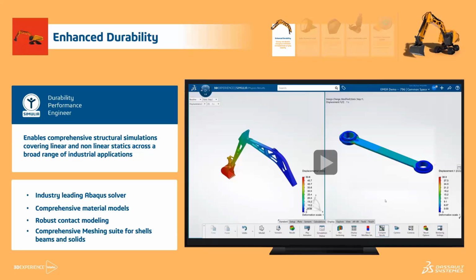Also, another advantage we have compared to our regular SOLIDWORKS simulation tools is advanced mesh. We have seen, for example, for the rod, that we have some hexa elements in the mesh, some cube elements, let's say. This is an advanced type of mesh element, and we can do it thanks again to the Abaqus technology.